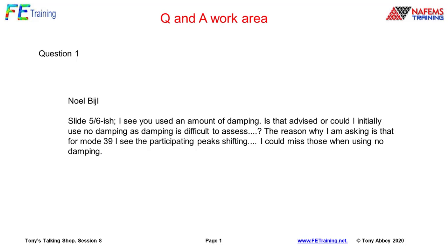I normally would put some form of damping in. If we're going to do a frequency response analysis, then it's important we put some level of damping in. If we want to be very conservative, we would put 2% damping in. That would be my usual typical lower bound. If I put zero damping in a frequency response analysis, I get basically crazy results at the resonance points, and then that laps over to the other points.